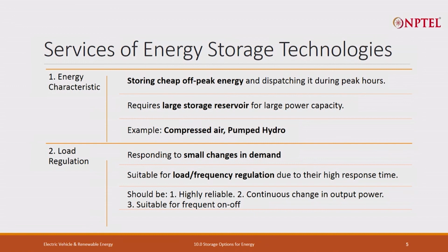Our energy storage technology should be highly reliable, with continuous change in power output being possible. It should also be suitable for frequent on-off conditions. Whenever I need, I can switch on. Whenever I don't need, I should be able to switch off. For example, for load regulation: flywheel, ultra capacitors, batteries. Not all the batteries, but yes, a lot of batteries.